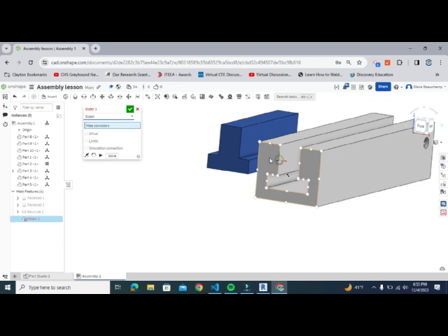One thing that's going to be very helpful for you is, once we hover over the plane, or the face, we're going to hit shift and hold that. What that does is, regardless of where I move my mouse, it locks all the mate connectors on that particular plane. The reason that's important is because, if you see, the blue axis, the z-axis, is pointing perpendicular to that face. And that's what I want. That is going to be the direction of the sliding, so it's going to be along that z-axis.